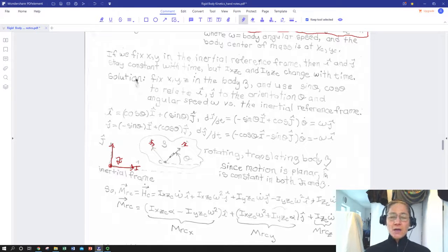And we used the same concept when we started initially looking at kinematics of rigid bodies, looking at a line at an angle with respect to a fixed reference frame, and looking at the change of that angle with time as representing the motion of a whole body. So we're going back to that same concept. We can define our little i hat and little j hat, just with some trig, in terms of our big I hat and big J hat, with cosine and sine respectively. We can just use theta and phi that are separated by 90 degrees and get those two expressions.